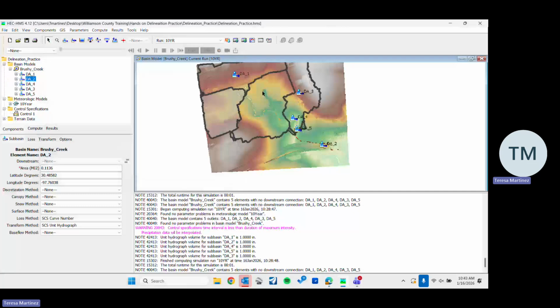But what you can do is, if you know that the shapefile has data, like it has a shape, you can bring it into QGIS as a layer and then re-export it as a shapefile, then bring it into ORD and it should show up. That's not hard to do. QGIS is free, and adding a layer is very easy, and then saving it too. And if you have QGIS, you might as well just do this processing in there, so you don't have to bring it into ORD at that point.